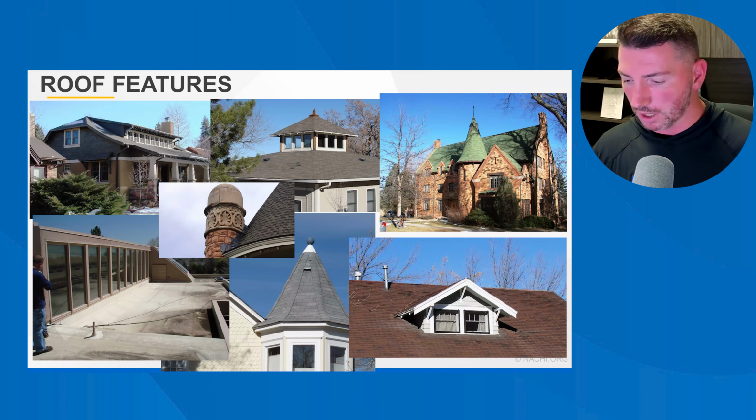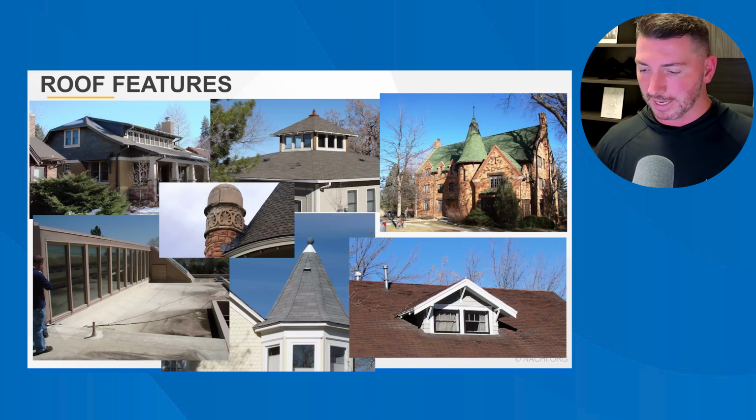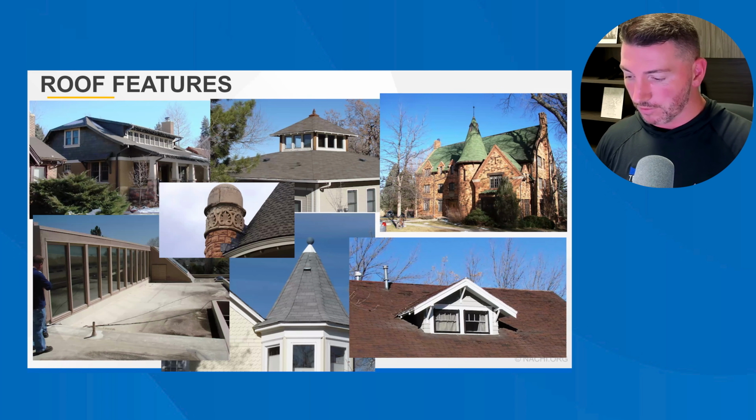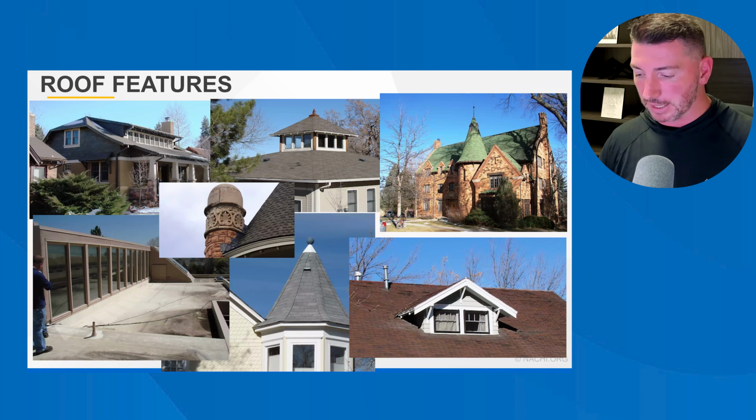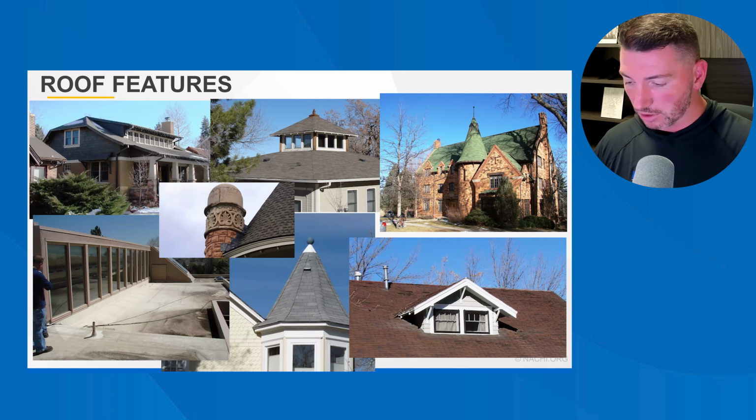Cupolas. Cupola, spelled Cupola. They're small structures built into the peak of a roof, often to provide light to the area below, and in some cases I've seen it to provide ventilation. The inspection concern is the roof framing supporting the cupola. Although the framing will typically be hidden behind interior wall covering materials, look for signs of movement such as cracking, and other vulnerable areas are head wall and sidewall flashing.